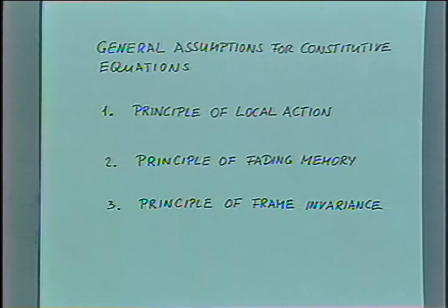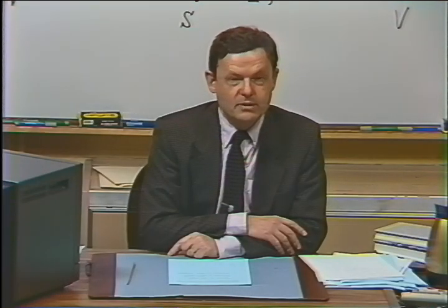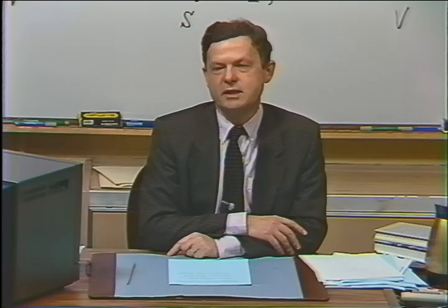And that says that the stress in a material element depends only on the strain history of that specific material element. It is independent of the history of a material element which is neighboring. Now, that's a very important assumption. It means that you can formulate your constitutive equations for homogeneous flows in the same way as you can formulate your constitutive equation for inhomogeneous flows.